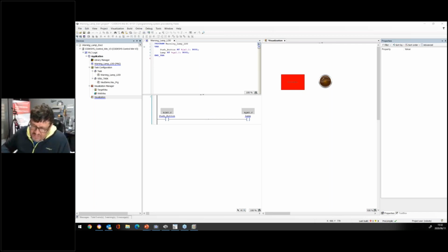I know a lot of those PLCs have a port that you can connect a serial communication to, and with the handheld, you can then program it on board onto the PLC itself, or you need to use an interface cable with a PC, with the software, so you can program that. I hope that answers your question, Andrew.